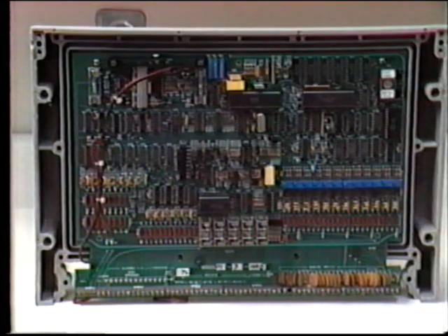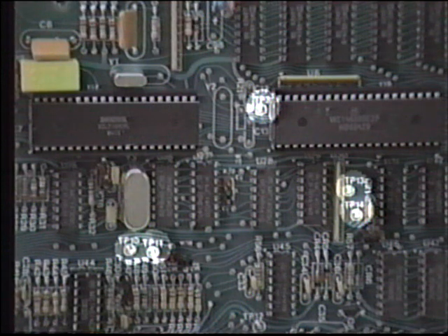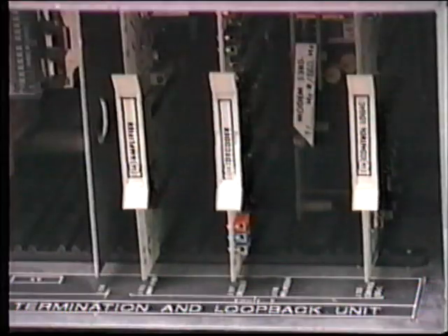Troubleshooting should be possible without disassembling the RTU. To achieve this requirement, certain test points and adjustments are made easily accessible and clearly marked. All of the printed circuit boards, the board slots, and other modules should be labeled for identification, as this will assist in substituting faulty components.